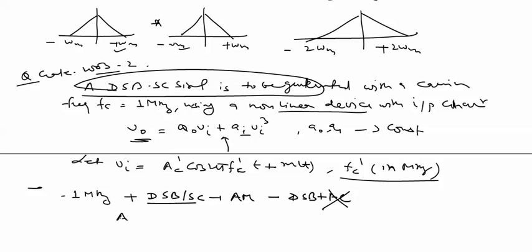In short, the AM waveform is a multiplication with one carrier additionally added. That is called AM. If the carrier is suppressed by any idea, it is converted into DSBSC. We want to generate DSBSC via a non-linear scheme. How is it possible?